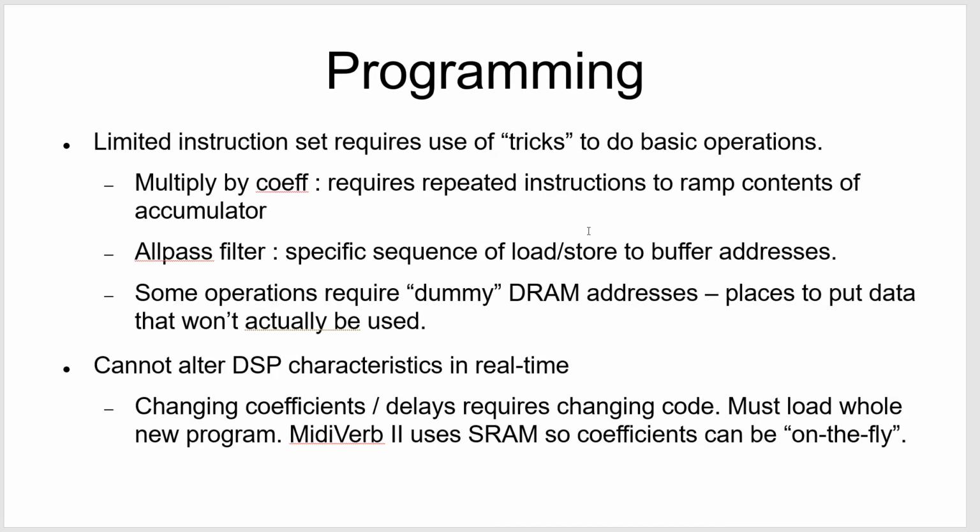The next thing is an all-pass filter. This is the most important thing in making good sounding reverbs, is how do you have an all-pass filter? A lot of people are saying, what the heck is an all-pass filter? If it's an all-pass filter, that's a wire. Well, the answer is, yes, you're right. The frequency response is a wire, but not the phase response.